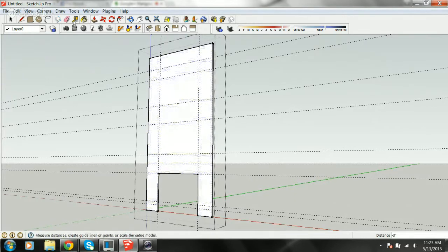Okay, so now you'll see in the image, if I just go up to the windows, it looks like I've got what I'll say is an 8 to 12-inch band around that second floor set of windows that's an accent in the brick. And it's inset from the right side on each side here. I just like to draw a line straight up and down. So I'm going to come here, grab that. I'm just going to say 8 from each side. So this is setting the boundary of that window opening.